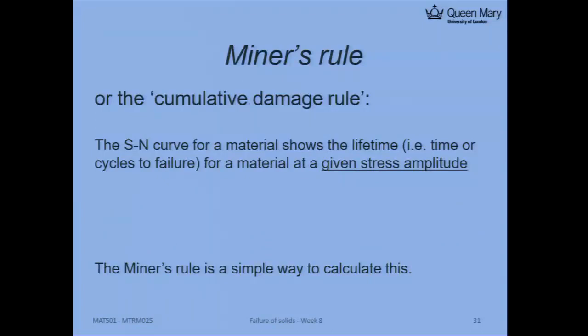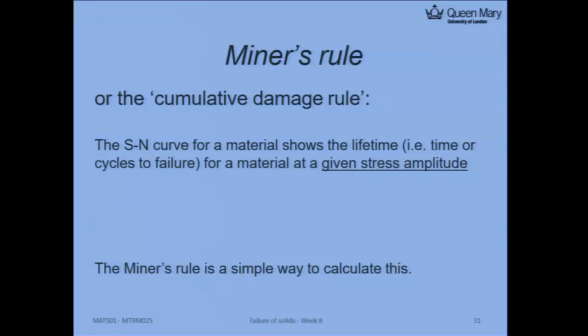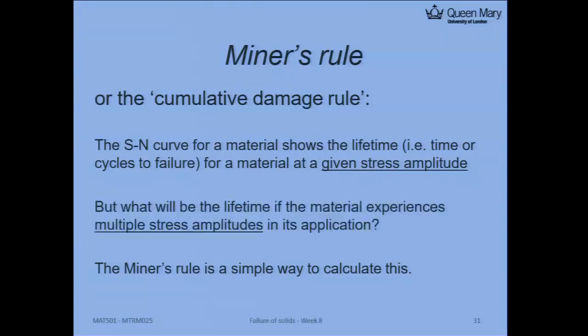So basically, again look at the stress fatigue life curve for a specific material. Most of the time, you apply a defined stress, like R equal to -1. But you can also apply different stress amplitudes. You increase the stress amplitude or reduce that. They're all giving you different cycle life. But suppose I give you a material, I ask you to apply different amplitudes, and I ask you how to predict the final failure life. So how to do that?